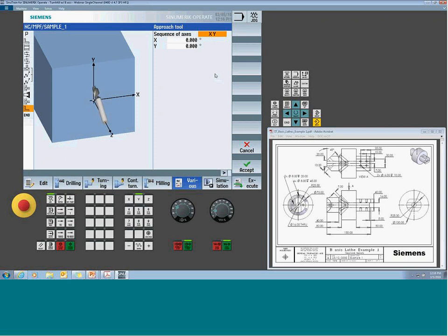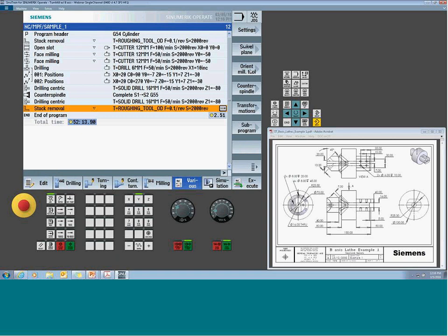But if I need to change the location of my tool and then come down and do something without moving my coordinate system, you can use the orientate mill tool. And in code, cycle 700 has that same variation. So you can do an orientate mill tool with cycle 700 as well on the G-code side, or a swivel plane.